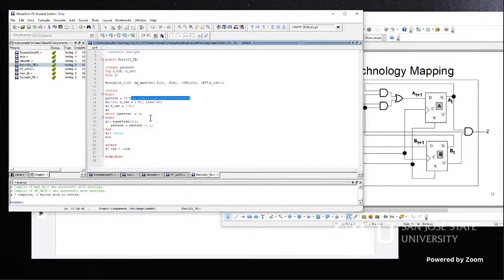And then I said that while the pattern is not 0, meaning unless this pattern becomes all 0, each 10 nanoseconds you pick up the MSB, pattern bit 31, put it into X, and then left shift the bit pattern by 1 bit.